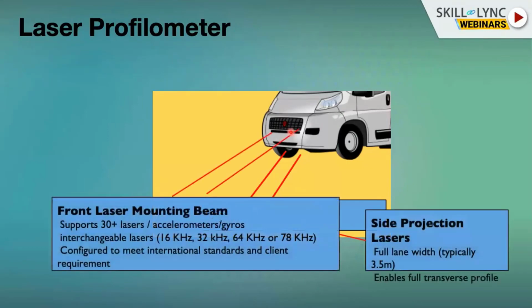It contains a number of lasers, a sensor called an accelerometer, and a sensor called a gyroscope, and using this combination, it continuously emits lasers. It measures the time the laser has taken to come back. It is a simple time and length principle. If the time taken to come back is more than the actual time, we can say there is some pothole,